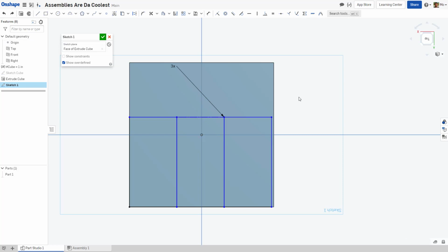So, to show you a new tool, let's kill 2 birds with 1 stone. Up here is the Midpoint Constraint. When I select it, I can select this point and this edge to lock that top right corner of my rectangular pattern to the midpoint of this farmost line of my square. Quick sanity check. All of our lines on our sketch are black, suggesting that our sketch is fully defined, which is what we are aiming for every sketch that we create.